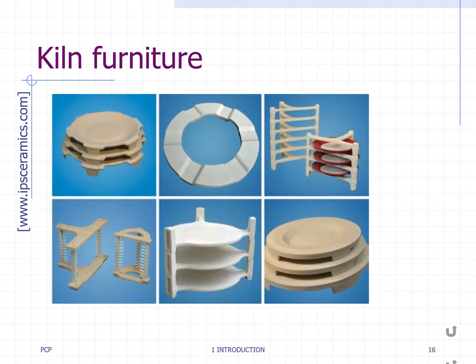Pieces of kiln furniture are used as supports for firing, sintering, and other heat treatment processes at temperatures over 1000 degrees C. They have many variations in either size, shape, material, or all these combining factors. They can be made of cordierite, alumina, or silicon carbide. They are refractory materials, which must resist thermal shock and present low creep rates.